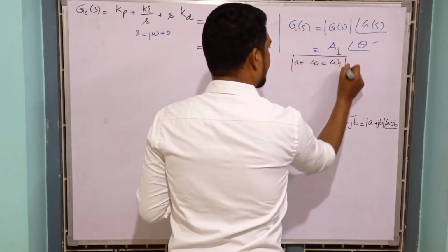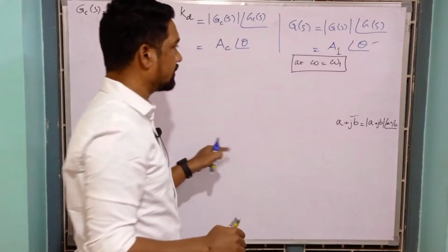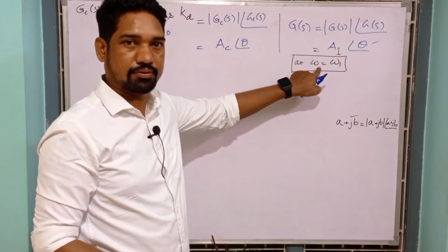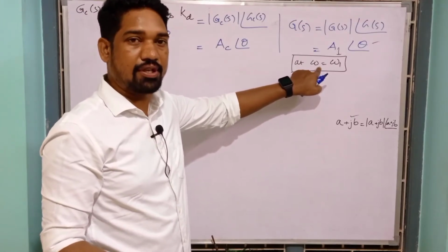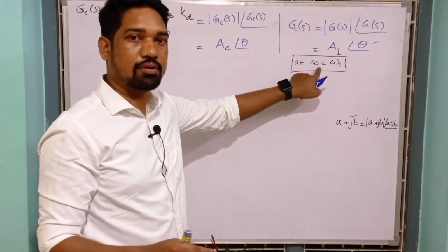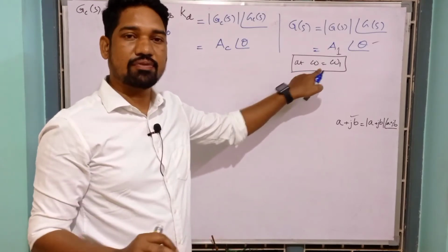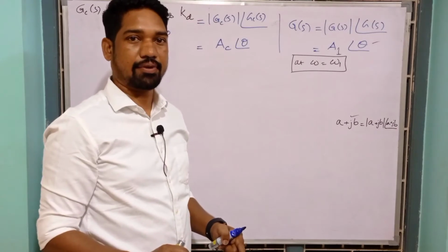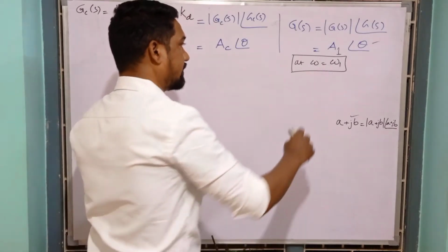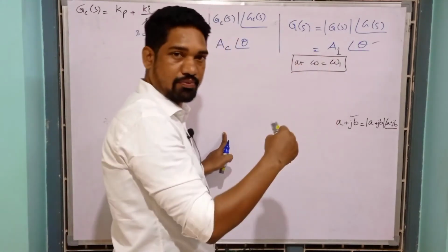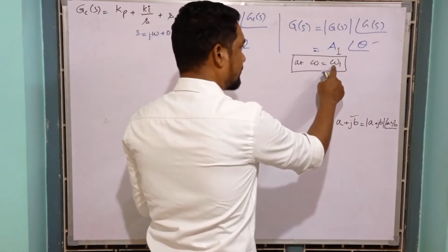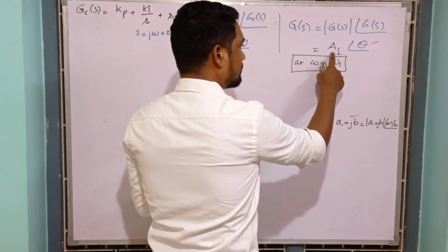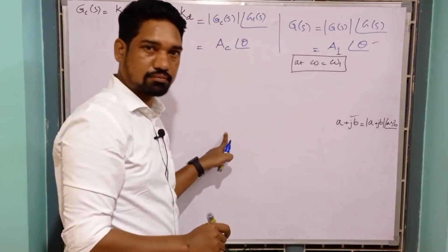Okay, so guys, this is highlighted. You could understand this only while doing the numerical. It will be asked: we need to design a PID controller so that it has a phase margin of something at a particular value of omega radians per second. That will become omega 1. So we will assume that to be omega 1, and when this value is plugged in over here, we'll have a magnitude, and that will be A1.